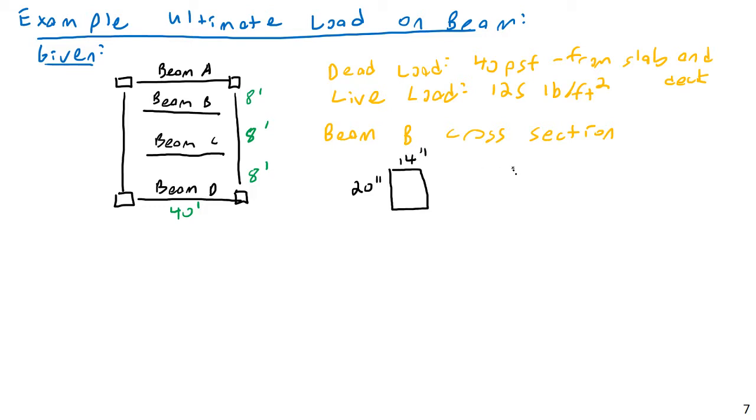made of concrete, and I am told this concrete now, as we mentioned previously, concrete's properties are much more variable than the properties of steel. Obviously, the ultimate strength and yield strength of concrete will vary quite a bit. However, concrete's density may vary slightly, but generally it's not going to vary much. And the reason is, if you remember back to our discussion of steel properties, at the end of the day, 95% plus of all the atoms in steel are iron. Actually probably 96, 97, 98 even are all iron.